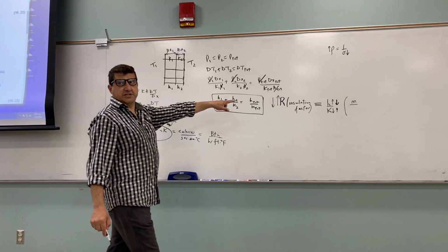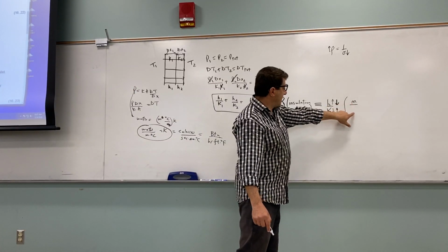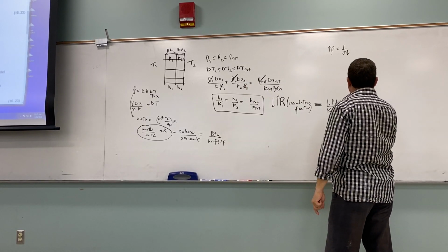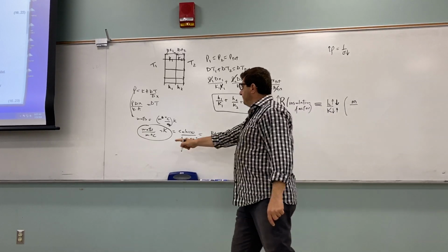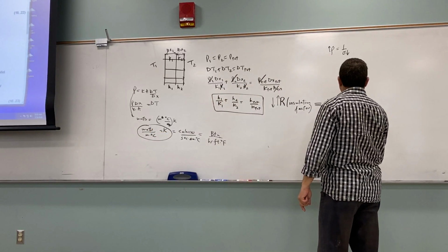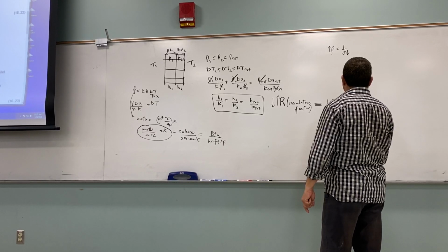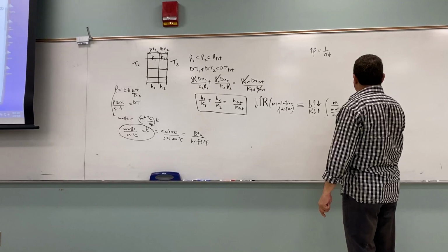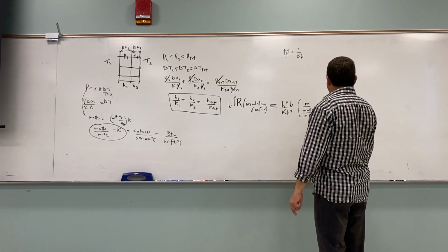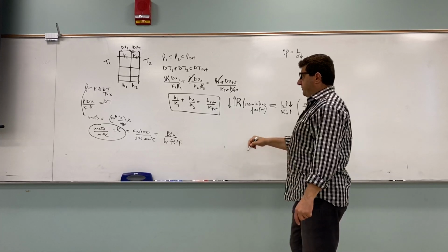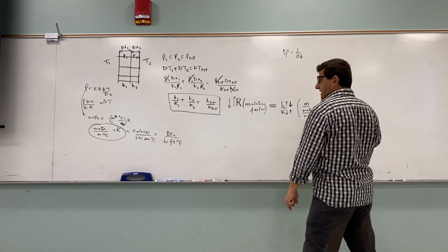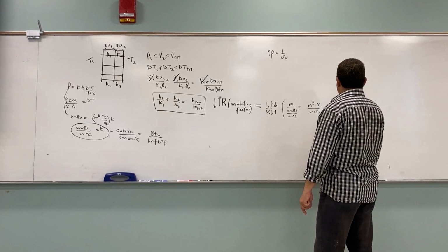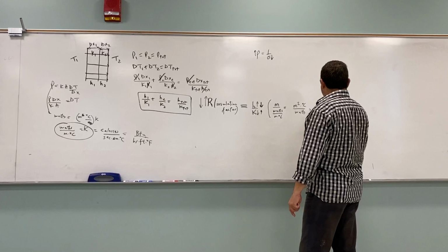So now the units of the insulation factor would be opposite of the K, plus you got the thickness of the material. So you got here meters divided by watts per meter Celsius. So then it's going to be meter squared Celsius over watts. Then of course you can have all the other versions too. So you can have centimeter squared Celsius over calories.